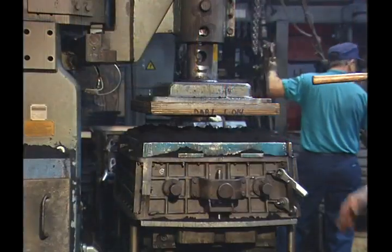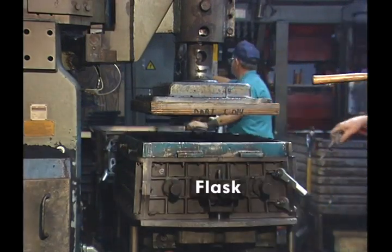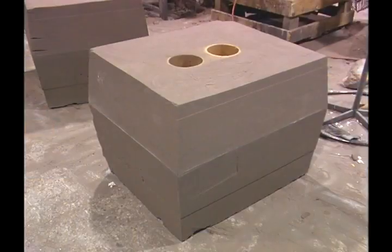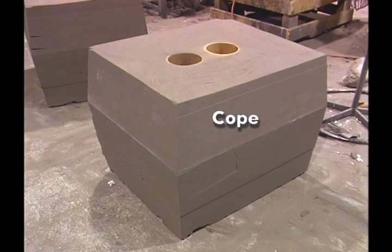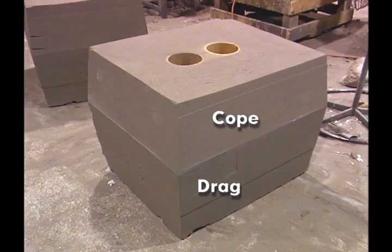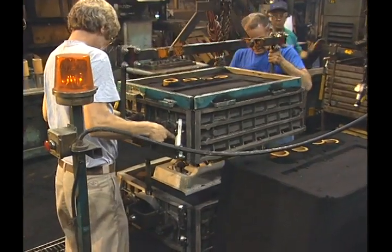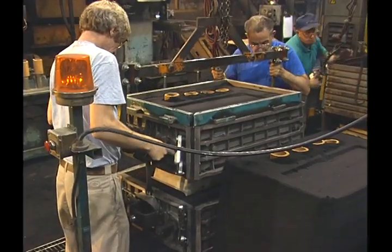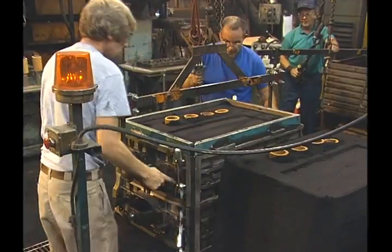Sand molds, made in halves, are built by tightly packing the sand around the pattern in a flask. The upper mold half is called the cope, and the lower half the drag. The mold includes one or more risers, venting provisions, and a system for transferring the molten metal to the mold cavity.